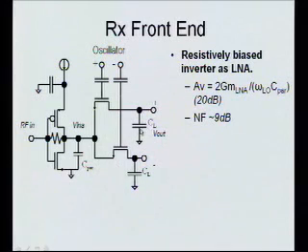These are big capacitors, so the one nice trick, this is a really standard direct conversion low IF trick, is to filter as soon as possible. So that as soon as you come out of the mixer, you immediately eliminate blockers before they ever become voltage signals. You just flatten them right away, and that prevents you from having to be really linear after the mixer. The gain is relatively high, it's about 20 dB. That's voltage gain.